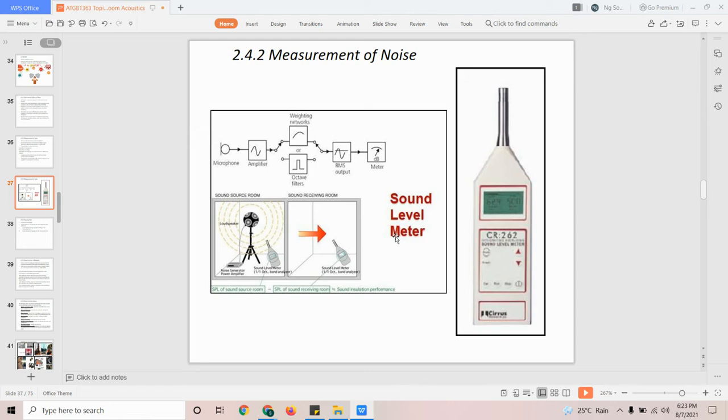So a lot of variable factors will affect the livelihood of people around if your construction site is near them. One of the ways to measure noise is this lah. Usually they'll just set this sound level meter up for a day or two and measure the sound during working hours and compile the report.